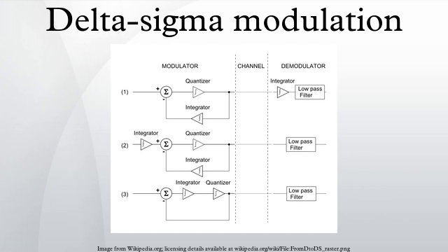On the other hand, a delta-sigma DAC encodes a high-resolution digital input signal into a lower-resolution but higher sample frequency signal that is mapped to voltages, and then smoothed with an analog filter. In both cases, the temporary use of a lower-resolution signal simplifies circuit design and improves efficiency.